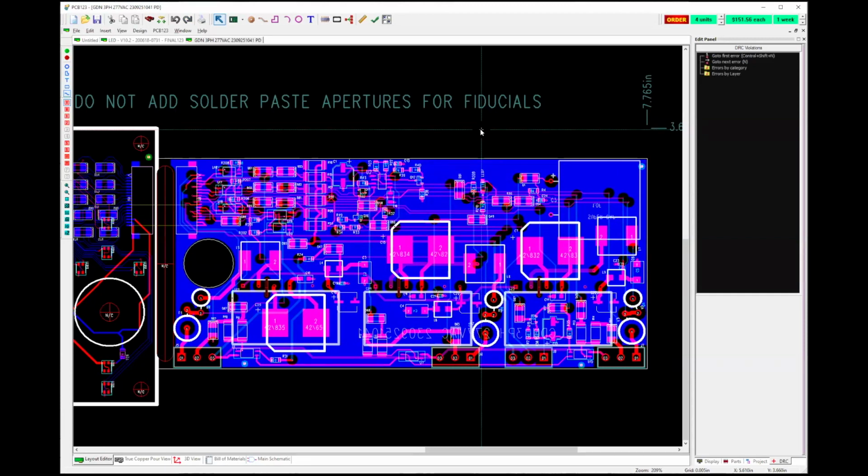And you certainly wouldn't want to auto route. Matter of fact, I wouldn't want to auto route pretty much anything using the auto route tool. Sometimes I'll use it as a reality check. Do I have enough room on the circuit board to actually do the design? And if it can auto route to 80%, just hitting the go button, then I pretty much know that I've got room to do it. Otherwise, I go in and wiggle things around, get a little more room. But again, differential pairs are easy to do. It's just not an automatic function.